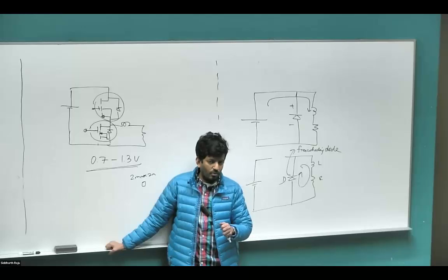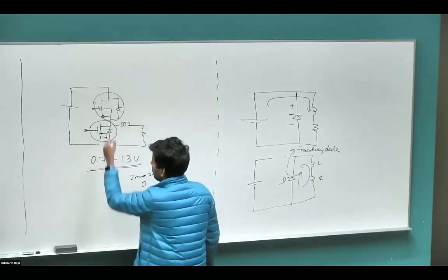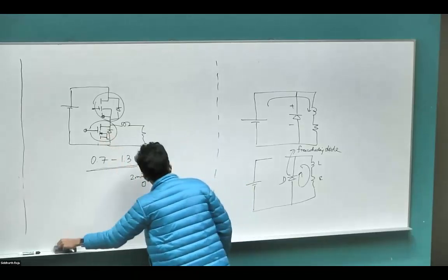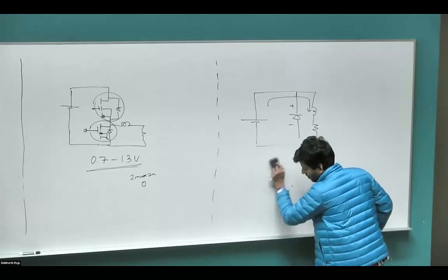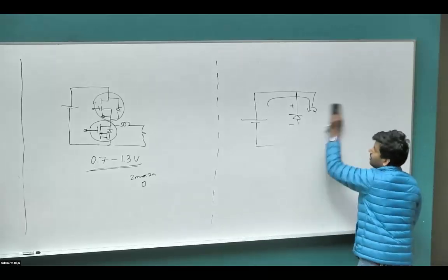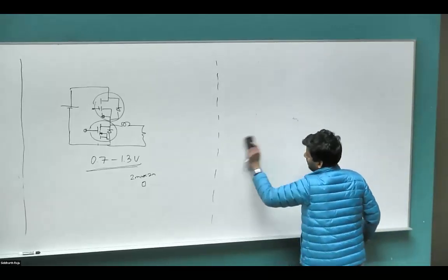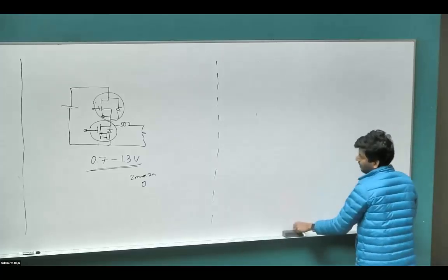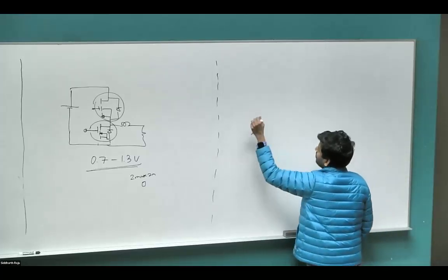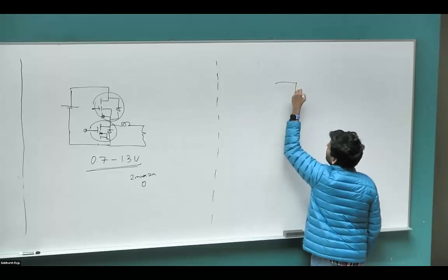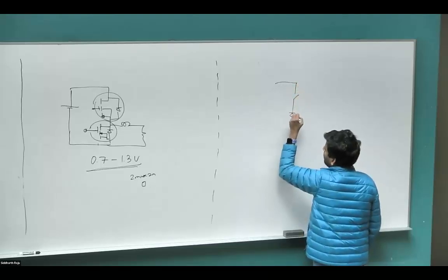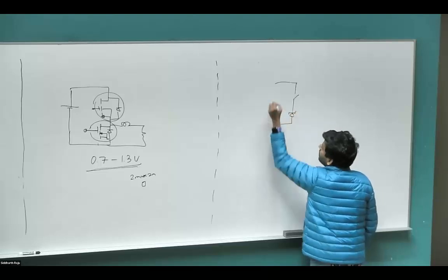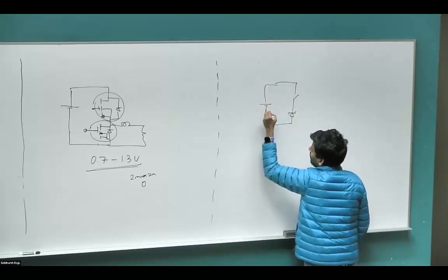What diode has a very low voltage drop across it? Yep, Schottky diode. So you can replace the previous diode that we had with the Schottky diode, which is basically the cathode channel replaced with a metal instead of a semiconductor, so that the drop across that becomes very tiny. So instead of drawing the MOSFET again, I'm just going to put a switch there. But there is a special class of diodes called Schottky diode.